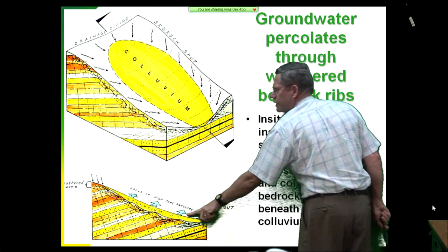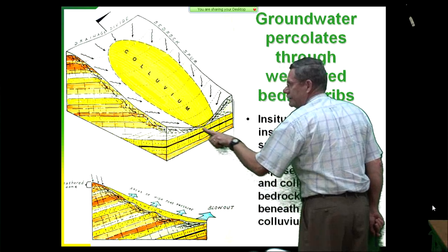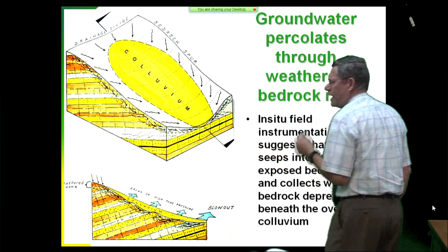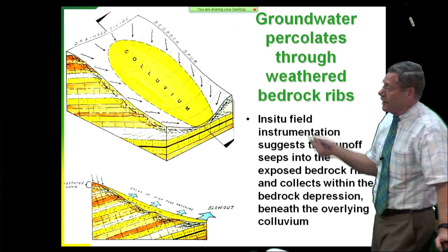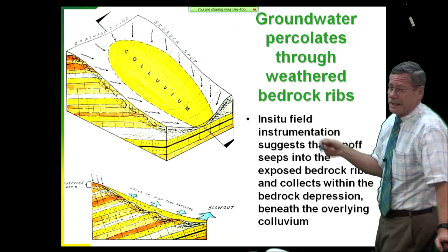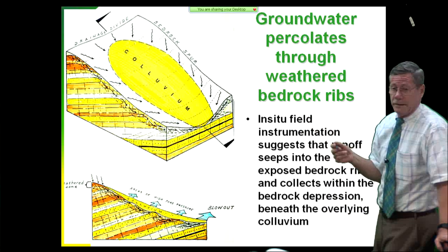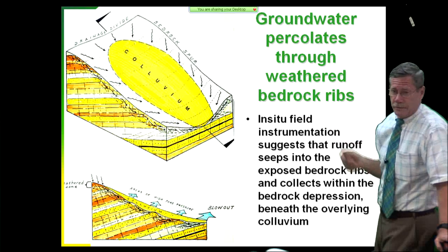So if I just put a trench subdrain right there, a little big trench subdrain, 50 feet long, backfill it with rock, that's the end of that. That's how easy it is to fix. So I've had the Forest Service doing these kinds of repairs since 1984, and it's the primary approach that the Forest Service uses all over the western United States.